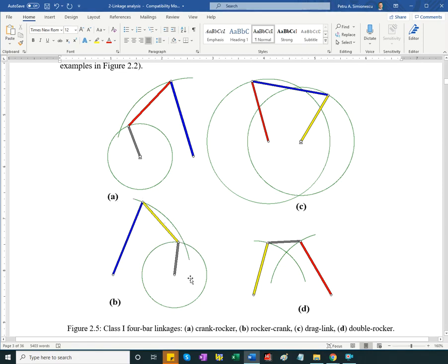Then the rotation of the shortest link pin jointed to the ground is guaranteed only if I have a flywheel in use. This would be the case of pedal actuated, like the old sewing machine, and they were 100+ years ago.